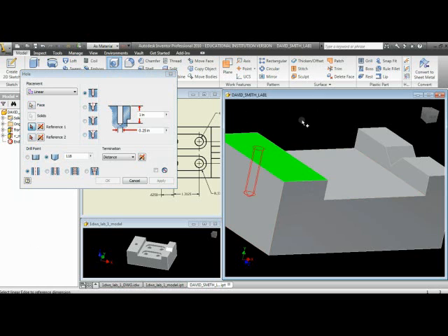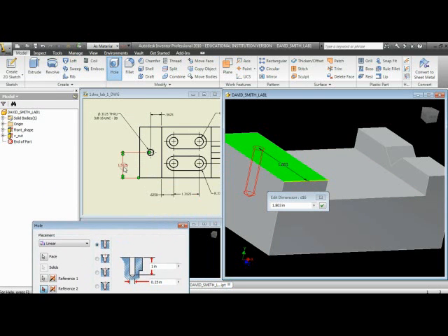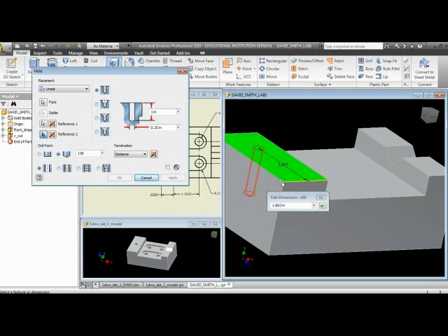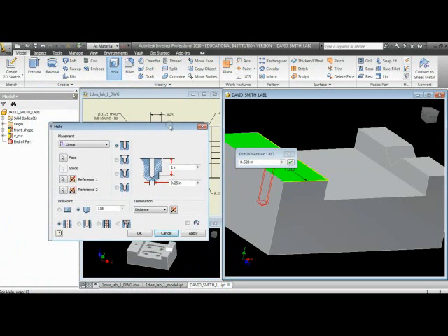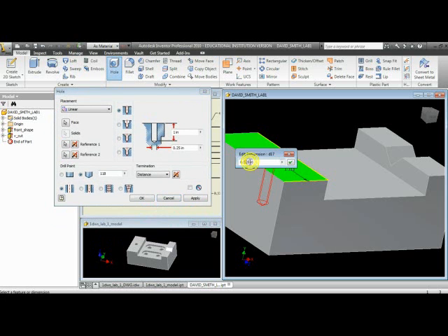different names. I might want to say front shape, and then on the second extrusion, if I click those twice, I might want to say V cut, so that I have an intuitive way of knowing where those different shapes are and what they are, instead of just extrusion 1, extrusion 2, and so on. So I'm going to hit the save button again.